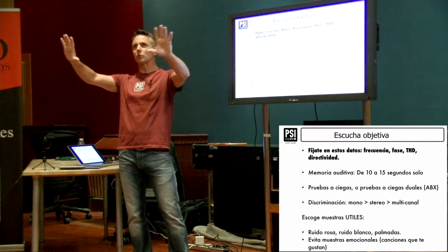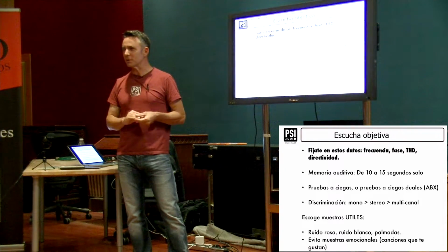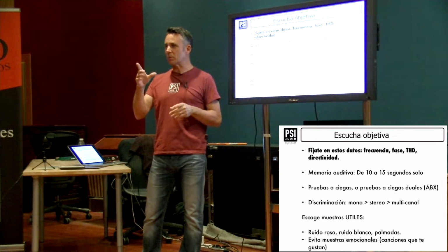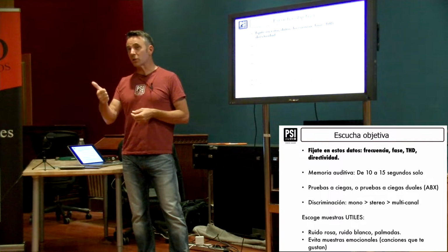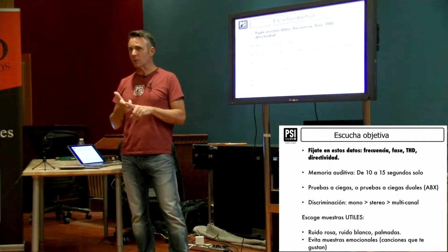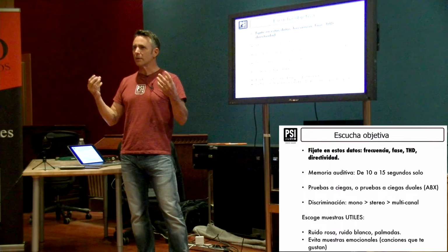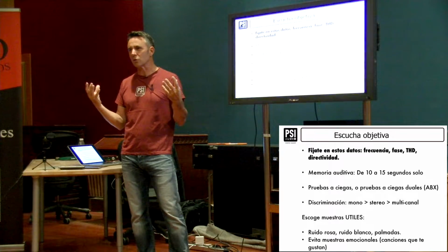Mono, and when you're testing a speaker, don't take your preferred song and listen to it in stereo in the sweet spot. I mean, that's not going to bring you much information. Mono really is a lot easier to discriminate between speakers in mono. And then use something that's useful and listen to white noise or pink noise. So that's a mix of all the frequencies, and then you can clearly see if there's correlation or not with that. It's much easier than listening to a song.